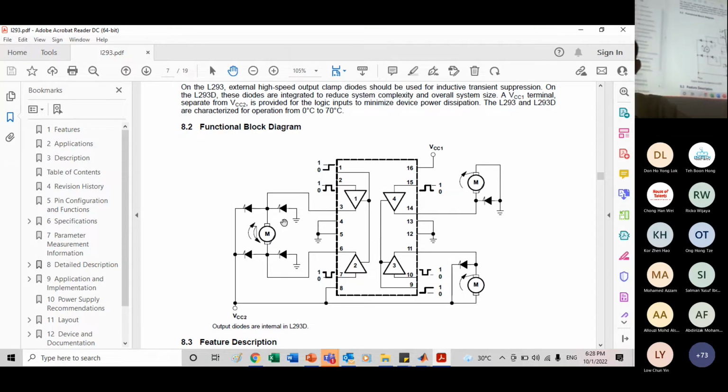A lot of students, when they look at this, usually they go Jalan Pasar to get a chip, happily come back, put it on a breadboard, and you see got diode, you say don't care. You just plug until it runs. Then you say, bullshit lah, can run. Of course, this thing won't damage your board on the spot. That is what happened lah. Can run, right? Tomorrow go demo in front of lecturer, cannot run already. Then I say, sir, yesterday running. Then I look at it, I believe you, but I still minus your mark because you don't put diode.